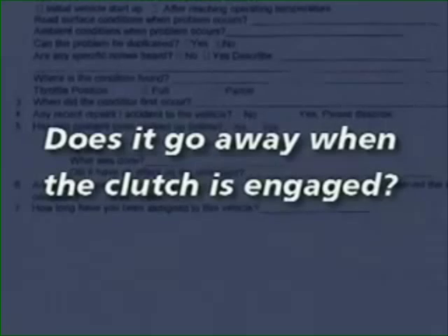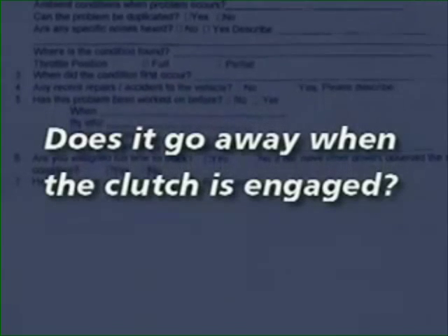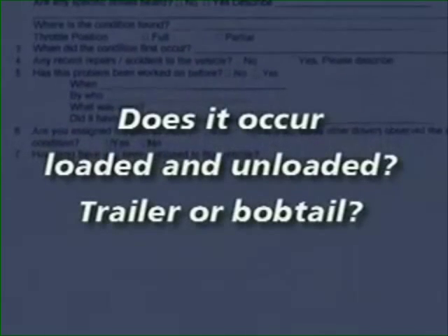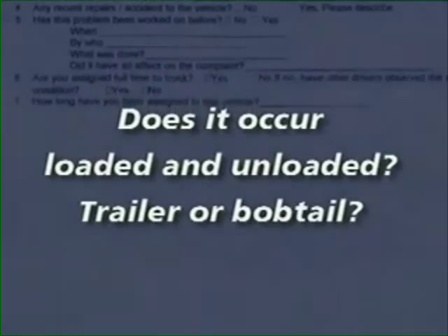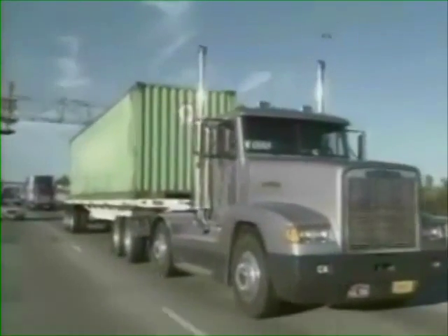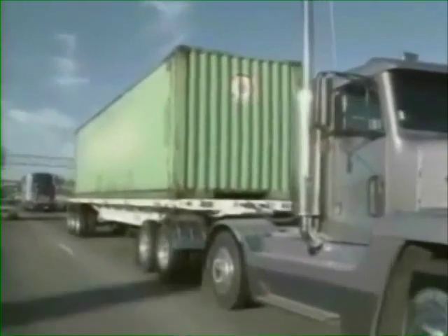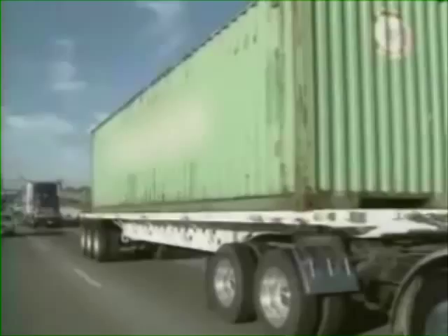Does it go away when the clutch is engaged at road speed? Does it occur under both loaded and unloaded conditions, or whether pulling a trailer or bobtail? Based upon these questions, it is possible to identify certain influences right away.